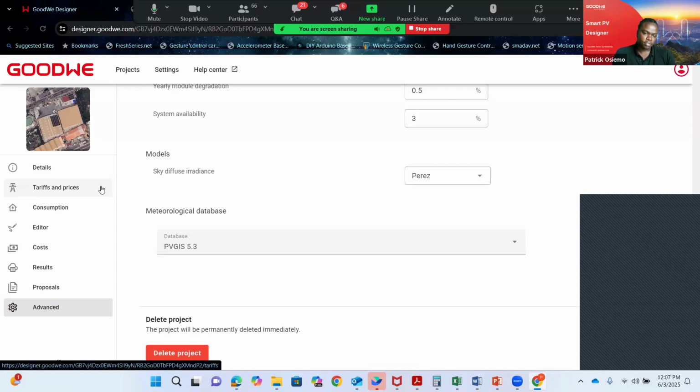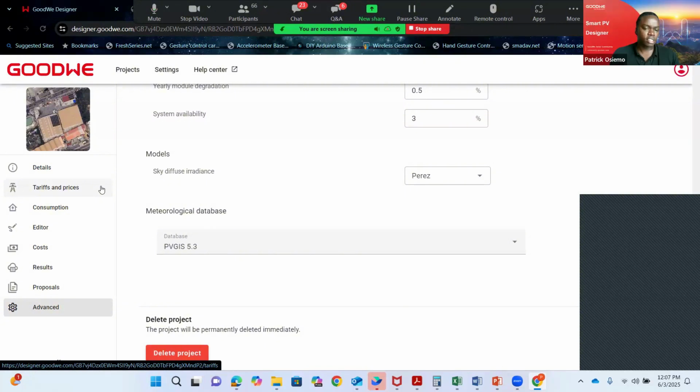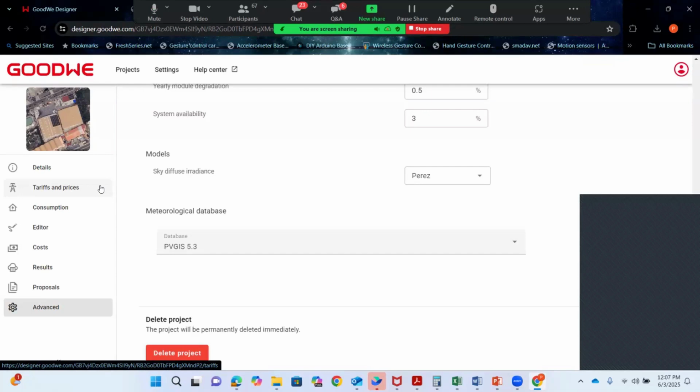So that is data transfer from SEMS to your third party. The other way is through SCADA. We have controllers that can be integrated using SCADA: our EzLogger 3000C, you can use these controllers and integrate through SCADA with Modbus TCP and Modbus RTU. And for the batteries, I didn't quite get the question. Yeah, me neither. Omoy, kindly clarify that on the batteries.